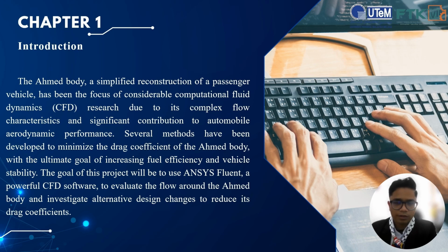Okay, for Chapter 1, I will start with the introduction. The Ahmed body is a simplified reconstruction of a passenger vehicle that has been the focus of considerable computational fluid dynamics (CFD) research due to its complex flow characteristics and significant contribution to automobile aerodynamic performance. Several methods have been developed to minimize the drag coefficient of the Ahmed body, with the ultimate goal of increasing fuel efficiency and vehicle stability. The goal of the project is to use ANSYS Fluent, a powerful CFD software, to evaluate the flow around the Ahmed body and investigate alternative design changes to reduce its drag coefficient.